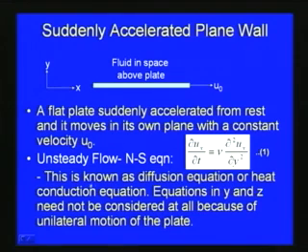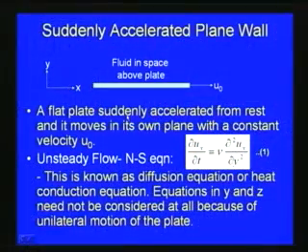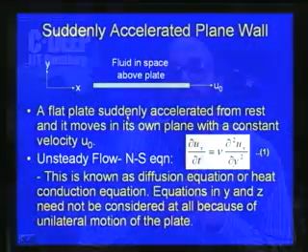Now we will consider another case where we can have an exact solution. It is called the suddenly accelerated plane wall. In the Couette flow and plane Poiseuille flow which we considered earlier, we considered the flow as steady state. Here we consider an unsteady problem. The problem statement is like this.